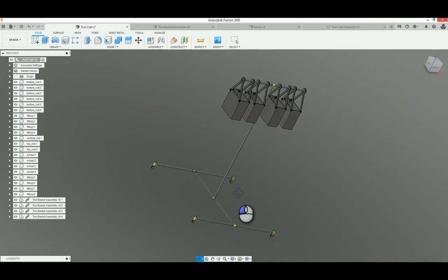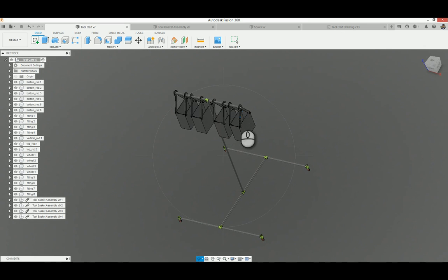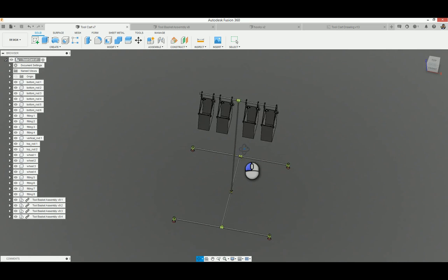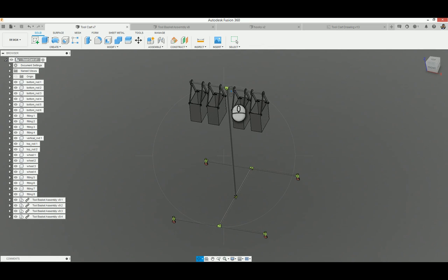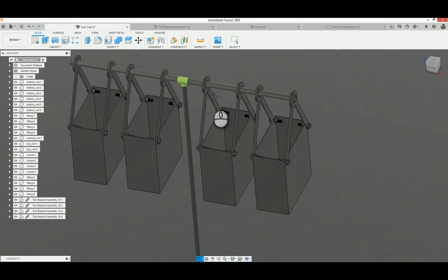We have the two baskets here being hung. Now you could see that we had assumed, for many calculations, a uniformly distributed load, but in reality what we have here is 4-point loads. So that's how design is an iterative process. After we select our pipe size based on the calculations, design engineers would come back and say, okay, this is practically how we hang the baskets. We would redesign it now for 4-point loads.